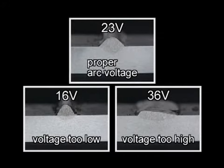These are macro sections of welded test plates showing the effect of changing the arc voltage while keeping the amperage constant at 200 amps. The arc length becomes shorter at lower arc voltages and the shape of the weld bead is convex. On the other hand, higher arc voltage causes a longer arc length and the shape of the weld bead becomes rather flat. The weld using an arc voltage of 23 volts is desirable, noted by the good bead appearance.